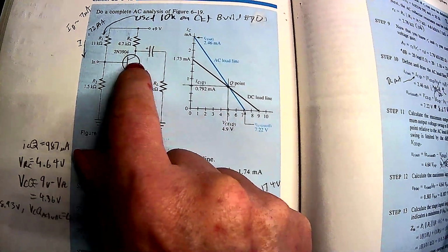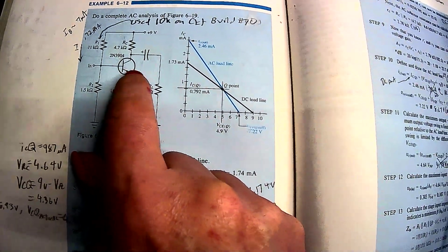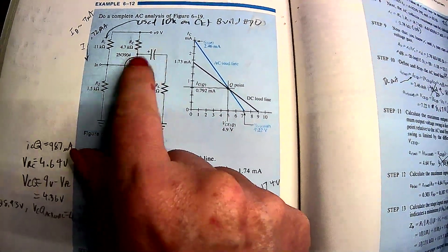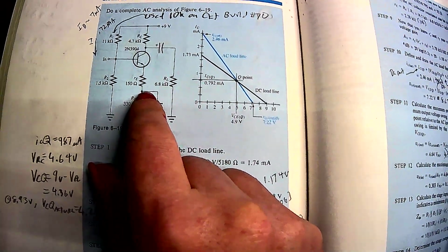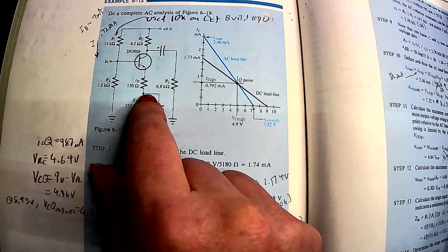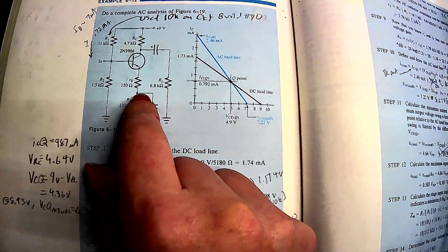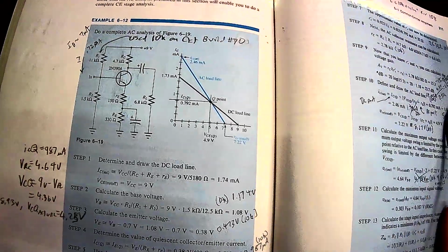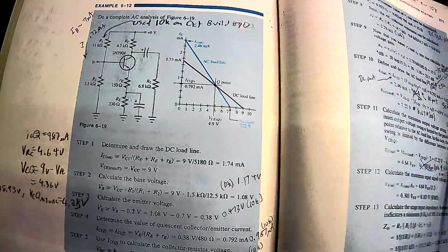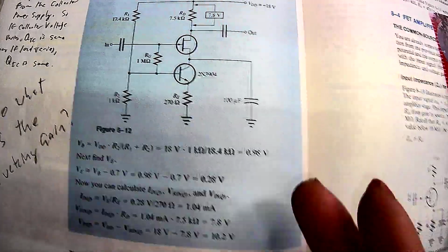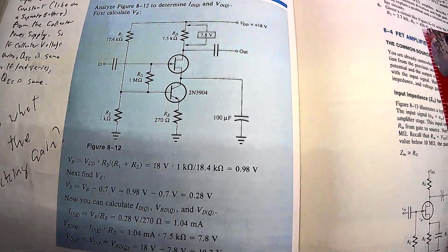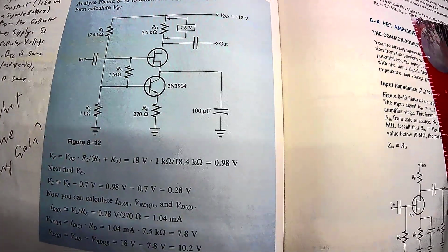But as a result, you could swap in a lot of different transistors with an amplifier like this, which happens to have a gain of about 15, and get substantially the same result. But you cannot do that with FETs because they just do not have enough gain, and again, the ESP guy talks about that. They just don't have enough spare gain for you to do that kind of feedback with.